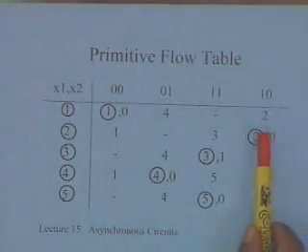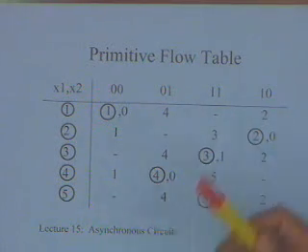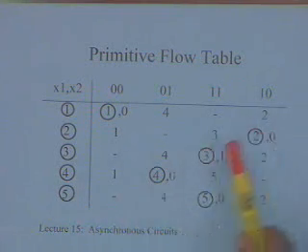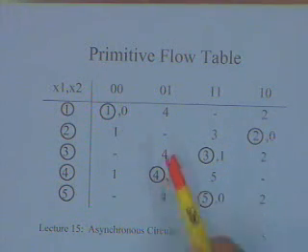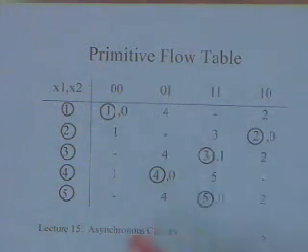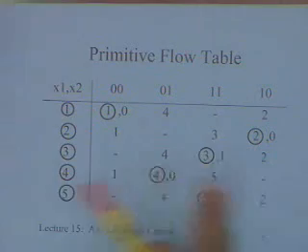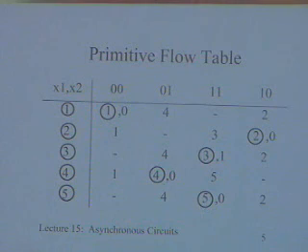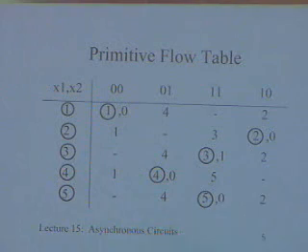The reason I am putting this to be 2 here will be clear from the process that we carry out. I actually would like that I immediately reach the stable state, as quickly as possible. I have no benefit in cycling through a number of states. So with that intent of making these two same, I mark this as 2. When an input change comes, I should try to go to the stable state. We will see how this works, and we will try to answer this question maybe in the next class, because once the procedure is clear, then this will also be clear. So you raise this question again if things are not clear.